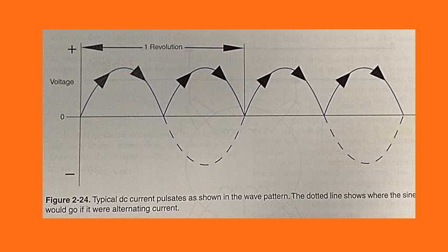The coils of a three-phase generator are located exactly 120 degrees apart. During each turn of the rotor, voltage is created at three different intervals. The separate voltages or phases are said to be 120 degrees electrically apart in time, or 120 degrees out of phase.